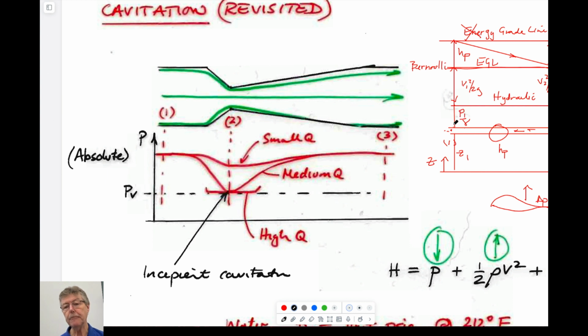Of course, if this pipe was constricted in some way, if it did this, then what would we expect to happen? Certainly Z1 and Z2 are the same. This velocity here, I suppose, since the area is bigger, has to be less than this velocity here. And so we could imagine that the grade line would actually be swapped, so it might look like this.